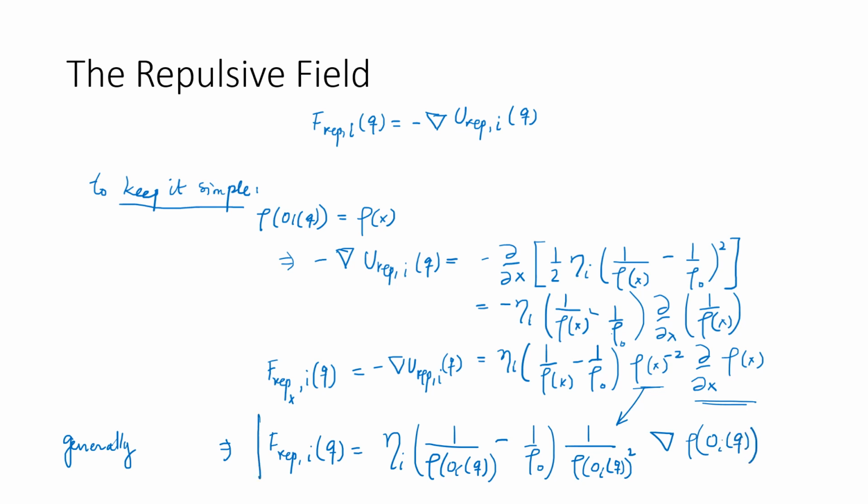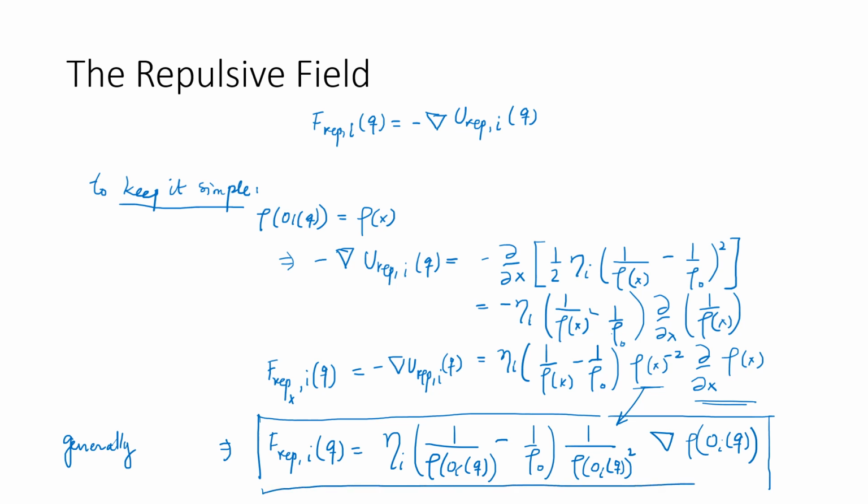So this is going to be your generic expression. We have kept it simple in order to derive it, but once we have derived it, we can further upgrade it to fit the general case when you have x, y, and z, all the influences added in. So this is your expression for the repulsive field when the robot is very close to, or within, the region of influence of the obstacle, and that is what we will consider while computing in one of the examples later on.